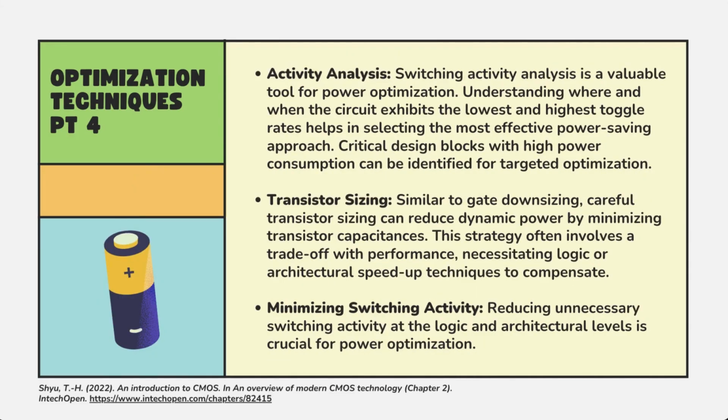Part 4. Activity analysis. Switching activity analysis is a valuable tool for power optimization. Understanding where and when the circuit exhibits the lowest and highest toggle rates helps in selecting the most effective power-saving approach. Critical design blocks with high power consumption can be identified for targeted optimization.